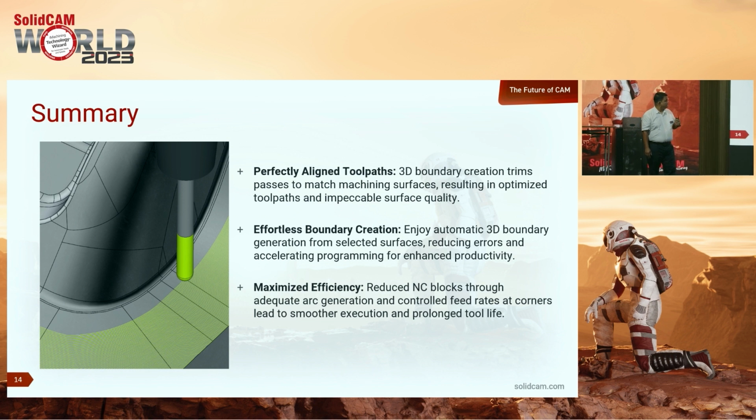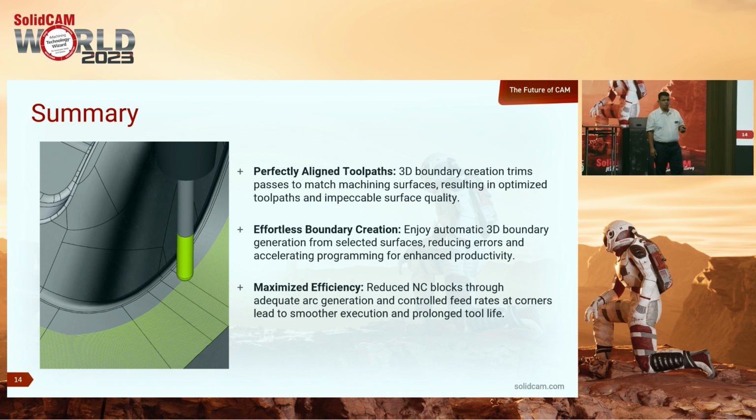And efficiency of the toolpath is much better than the Turbo 3D HSM as well as HSM because of the arc fit function that we have introduced inside that can totally reduce the number of blocks in the G code, resulting in faster cutting. We have already seen it on the machine. We can sense that it's much faster than the previous engines.